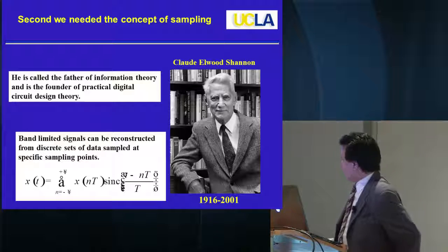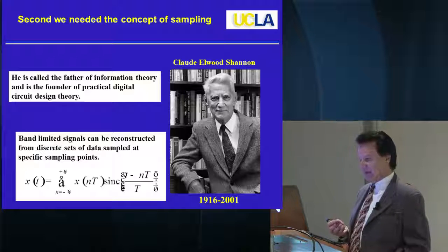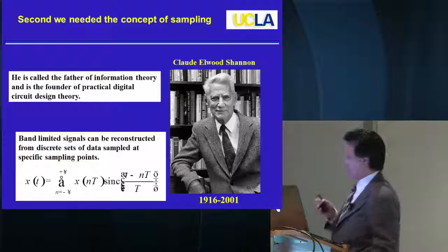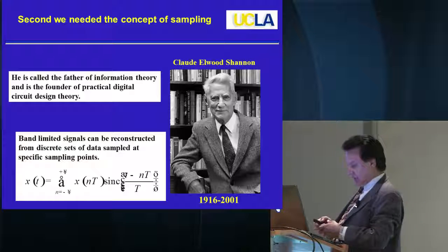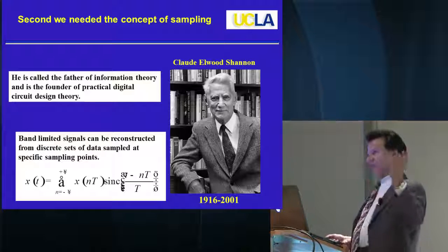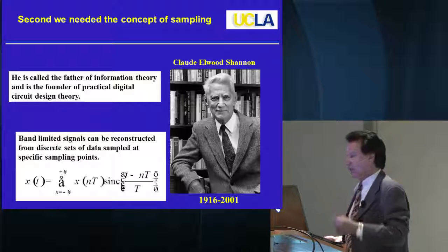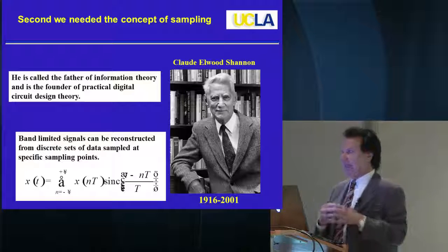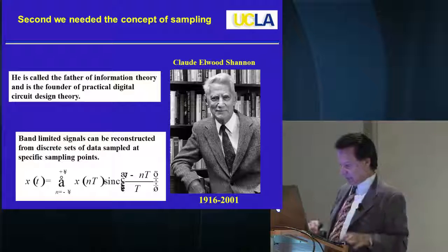The most important thing that came of Shannon's work was that band-limited signals can be reconstructed from discrete sets of data sampled at specific sample points, and that revolutionized everything. In other words, if I have a signal which is band-limited in frequency, I don't need to know the signal at every point. I only need knowledge of the signal at some specific points, and that changed our whole life, how we do communication, all the codings, and so forth.